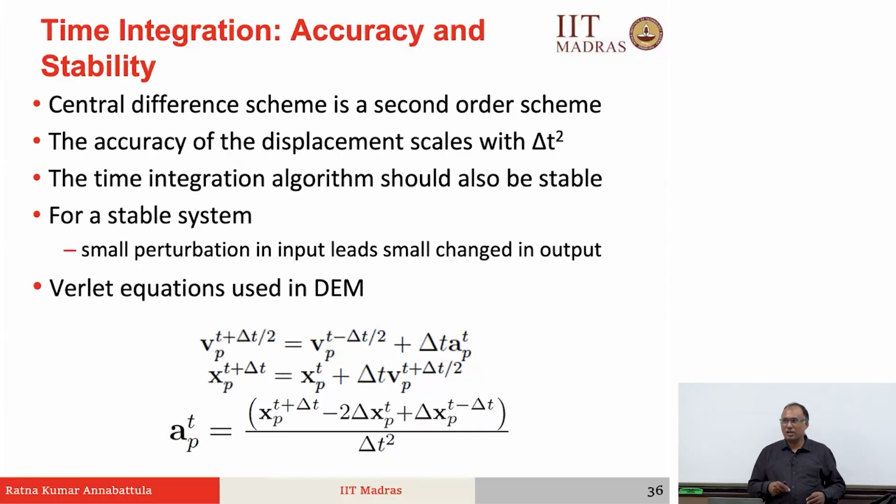So if some of you have done mesh convergence in FEM, mesh convergence is about the size of the element. Similarly, you can also do a convergence on the time step. So you choose different time steps. After some time the solution will not change. Further reducing the time step will not change the solution. Then whatever is the largest time step at which the solution stopped changing, that is the meaningful delta t that you need to take.